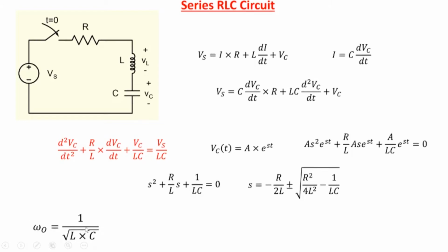Later, in the next lecture, we may call it the resonant frequency of this circuit, 1 over square root LC. Right now, it's a frequency characteristic of the circuit, related to L and C. And we can define something called Q, the quality factor, as omega naught L by R. We'll see the significance of Q in a minute.